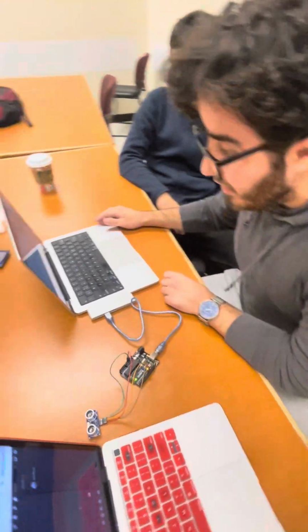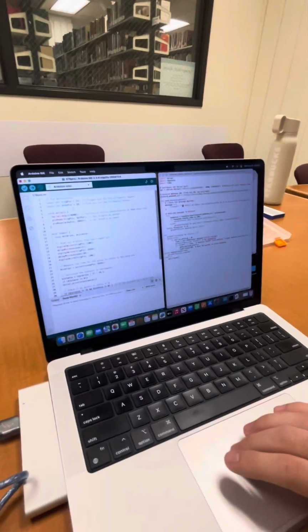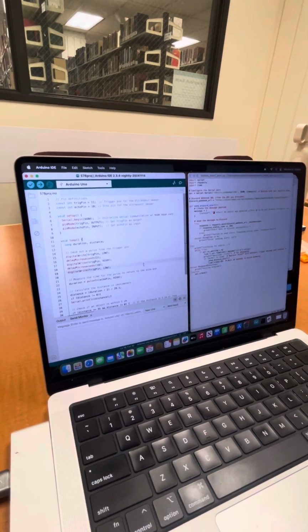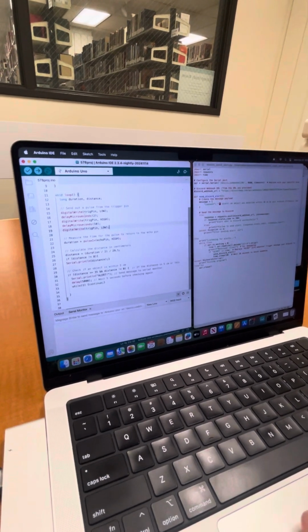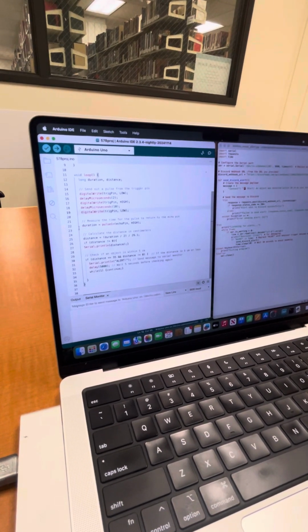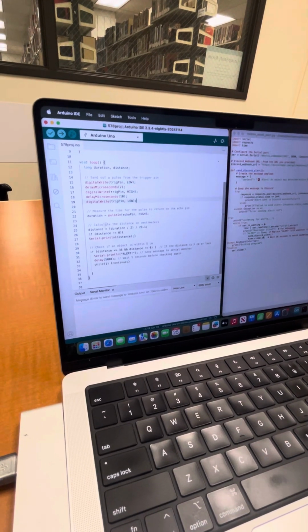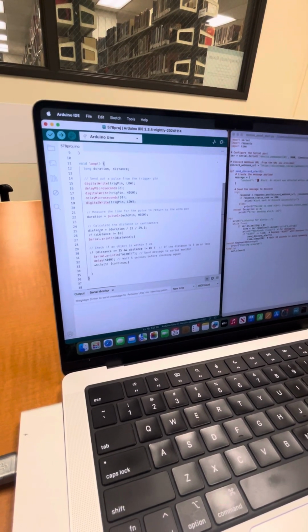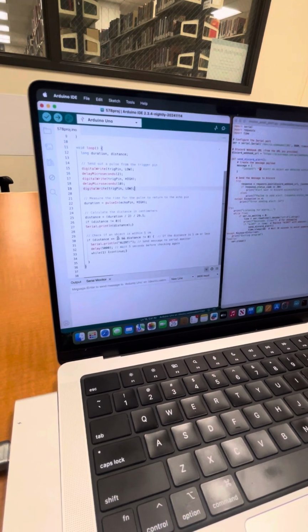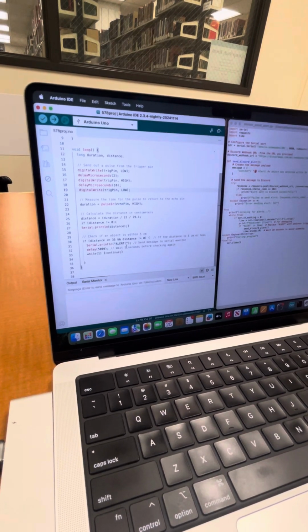And if we come over here to the code, as you can see here in the Arduino script, it's all the basic stuff. And where it's more important here, this just gets the stuff from the ultrasonic sensor. And here's where the code happens. We get the output of everything that's close. Then we calculate the distance, and then we check if the distance is X amount. This amount can be changed. And then we'll send an alert to the user, which tells them that something invaded their home.